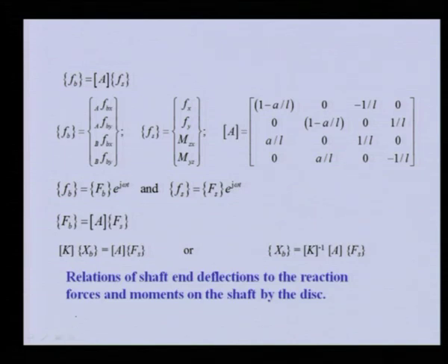Like this. So, this is the bearing force, this is the shaft reaction forces, and this is the A matrix. You can see the bearing force has 4 components corresponding to bearing A in x and y direction and bearing B in similar 2 directions. The shaft reaction force contains not only the force in x and y direction, but also the moment in 2 planes, that is zx and yz plane. The stacking we can choose according to our convenience. In this particular case I have chosen force in x and y direction first and then the moments.